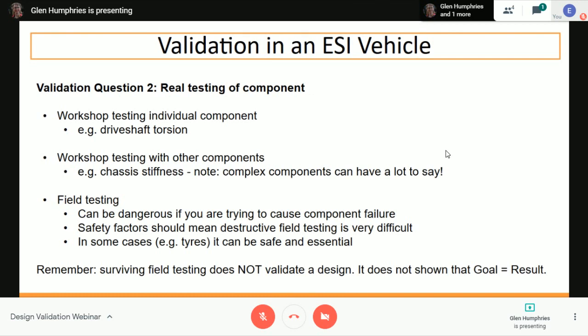So of course it's going to twist a bit elastically as you increase the weight. Record the weight and compare it to the angle. And if you record enough data points, you can come up with, rather than a force displacement curve, a torque rotation curve. And this will tell you really useful things about the elastic range, the plastic deformation range, what happens near rupture. And again, this is great data that you can bring to either a design event or a validation event as appropriate.